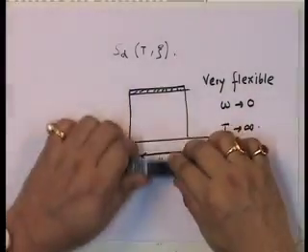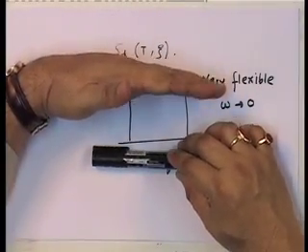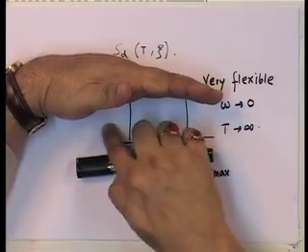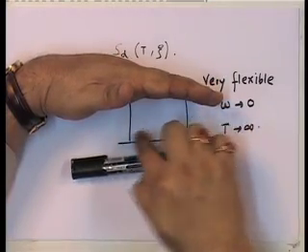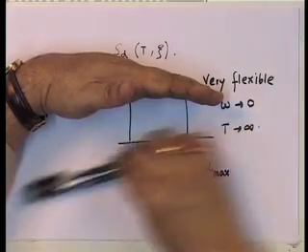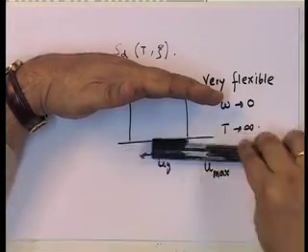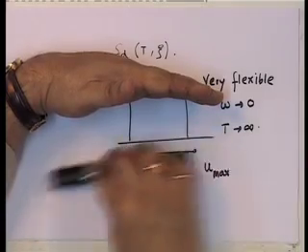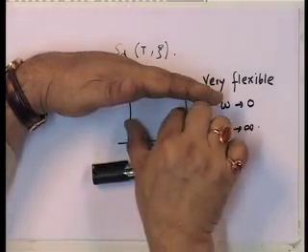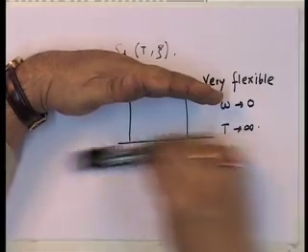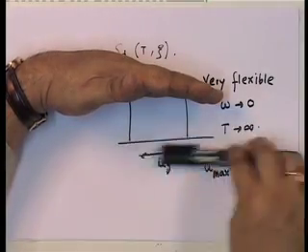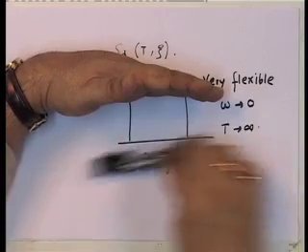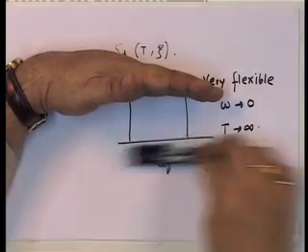If you look at the maximum deformation, this does not move. Why? Because this is infinitely flexible. As this moves, the mass has inertia, and the ground motion is not being transmitted because these are so flexible they cannot transfer any force. So, this is what is going to happen. As far as the mass is concerned, it does not see it.